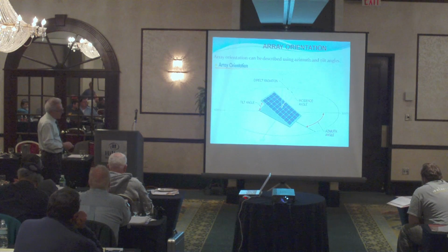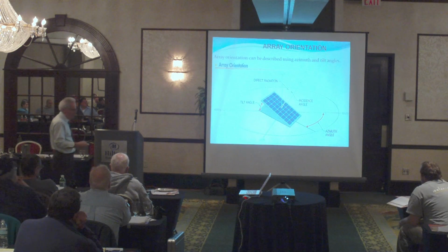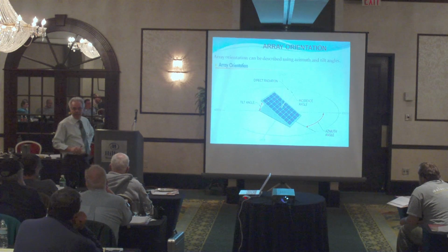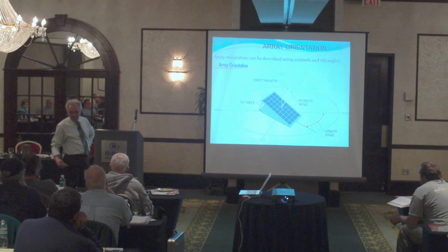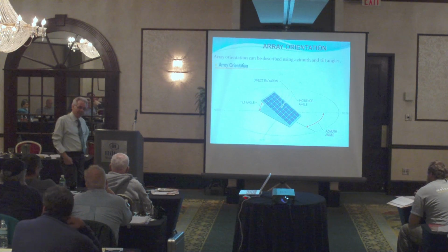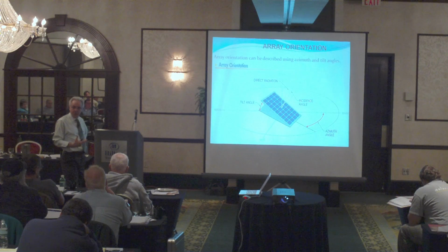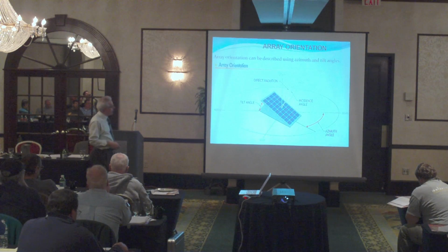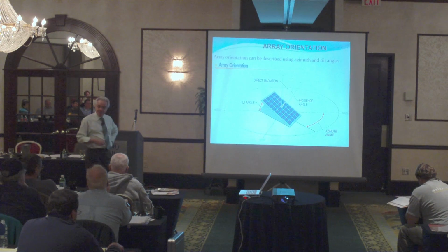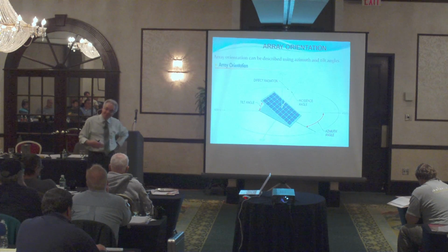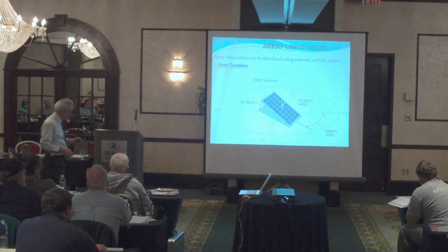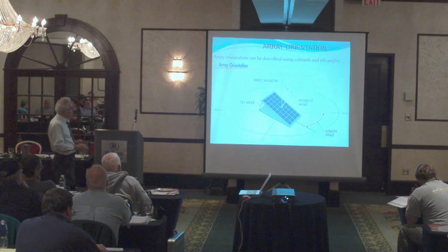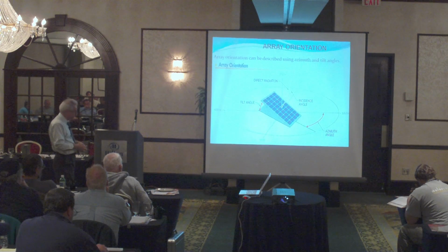Okay, nice. What happens eventually is what we do in practice. We set up the tilt angle, we set up the azimuth angle, we bolt them down, and we're done. That's the best performance that we can get. But ideally, you would want to be able to vary that. Should I go and change the tilt angle in winter and summer to get maximum performance out of it? Well, we'll talk about that when we do a design. So this is what we mean by the tilt and the azimuth angle.